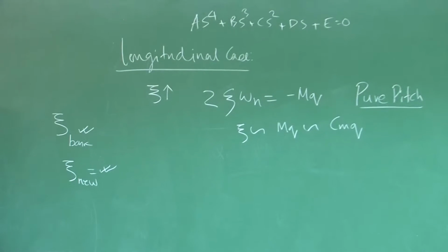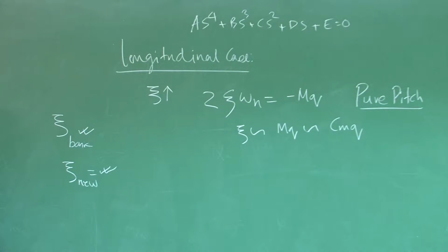So you know very clearly zeta will change with altitude as well as dynamic pressure. So you have a zeta basic, for which you have designed the airplane for a given altitude, but you are now operating at a different altitude, let us say.